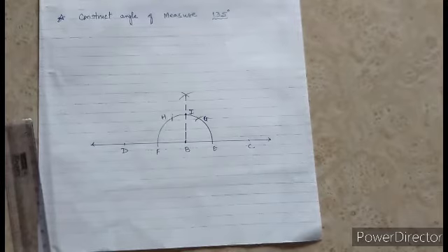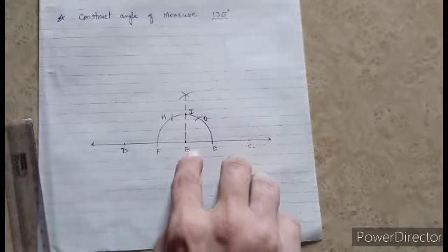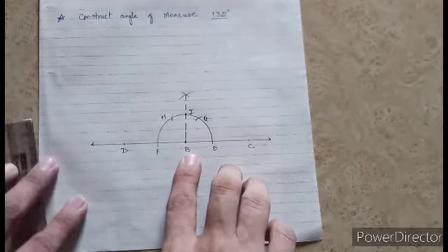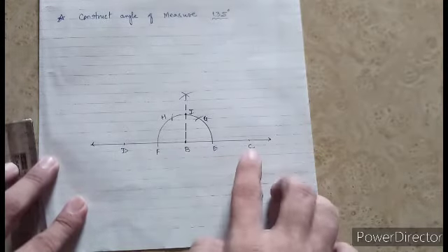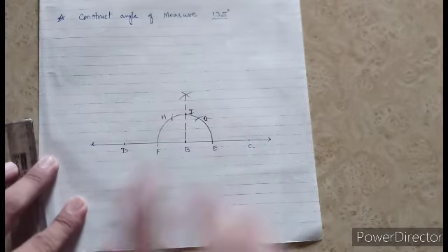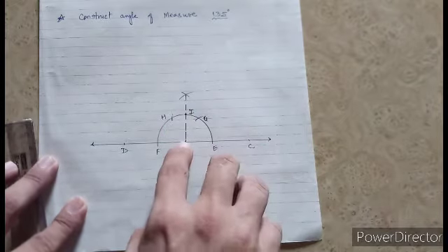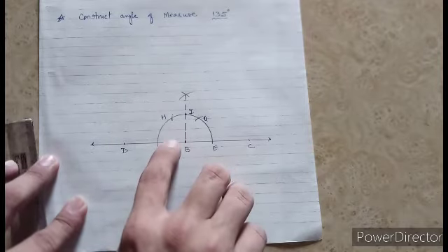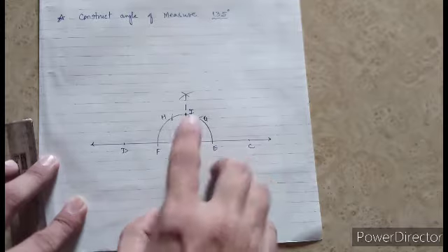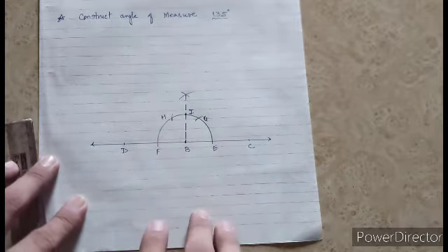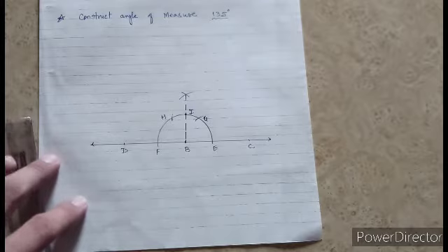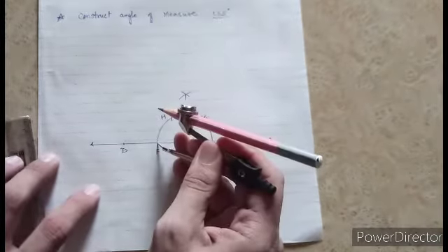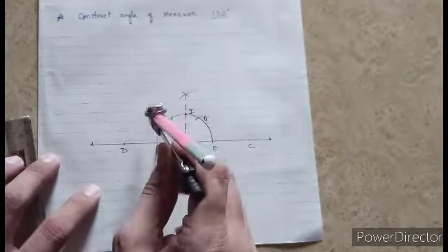On the left hand side, on angle IBF, we will construct an angle bisector. As we can see here, this IBC and IBF both are 90 degree angles. If we construct a bisector on this side, it will give us half of 90, that is 45. This angle is 90 plus 45. 90 plus 45 will be 135. So you have to take I and F as centers one by one, and taking any arbitrary radius, ideally more than half of IF.